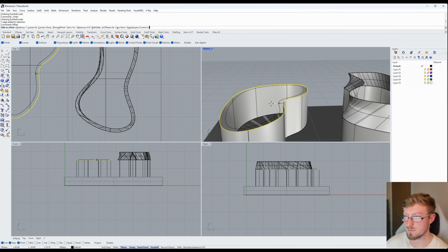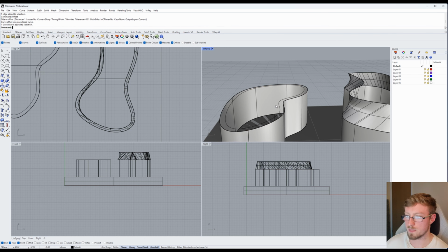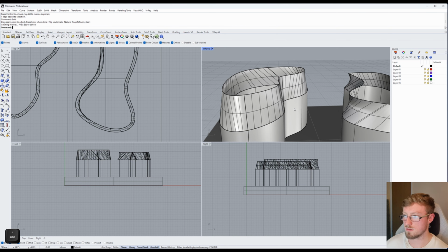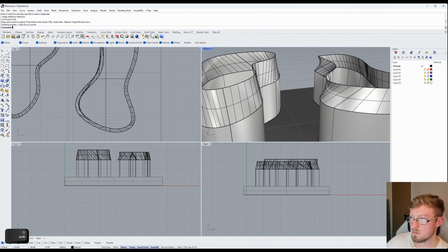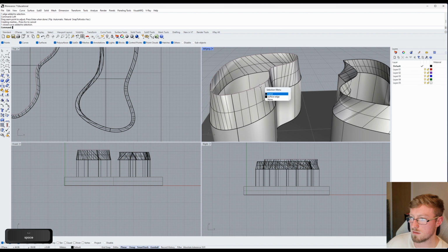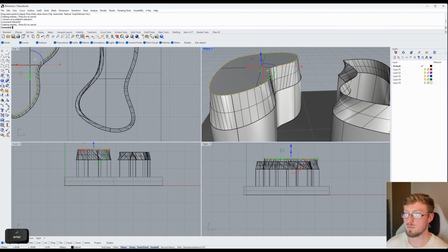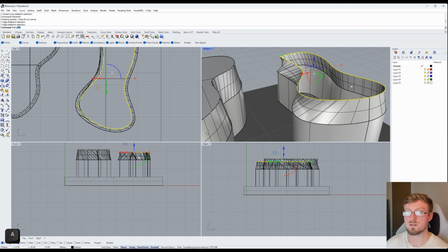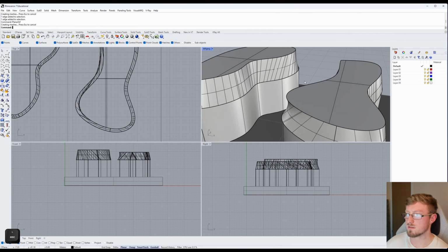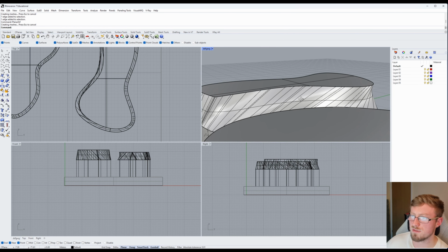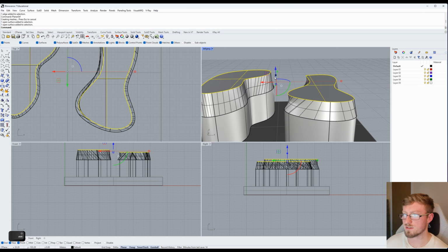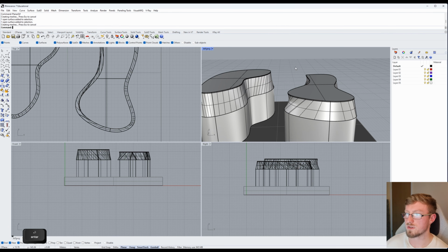Offset. Yep. Bring that up. This. Off. And then let's planar. Close it as a roof. This one isn't going to work, is it? Here it is. Not too sure why that wasn't working before though, if it's closed. Not too sure on that. Anyway, let's add some height on this. 1.2.